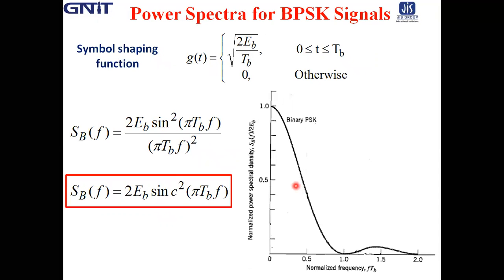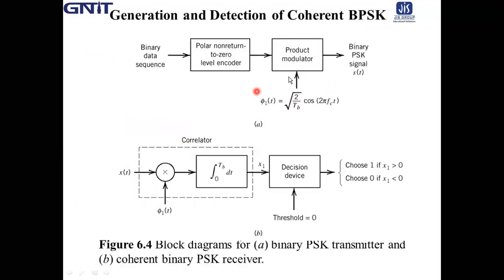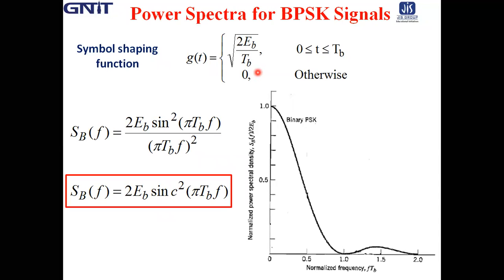Next is the power spectra of binary PSK signal. From the modulator in the first figure, the generation technique figure 6.4a, we see that the complex envelope of a binary PSK wave consists of an in-phase component only.